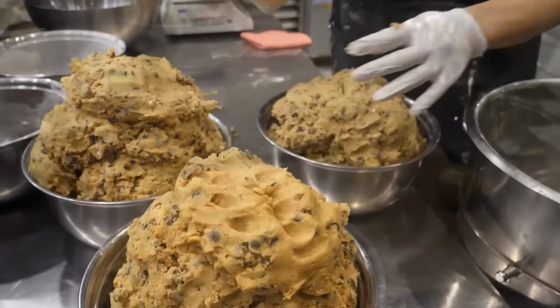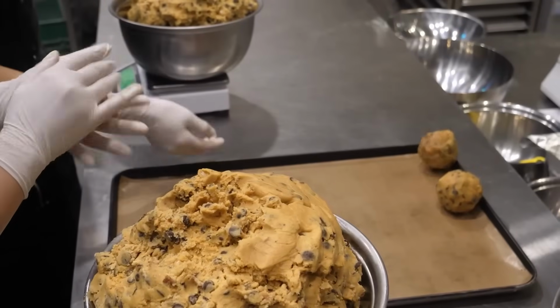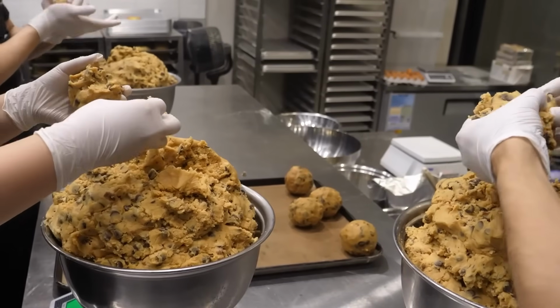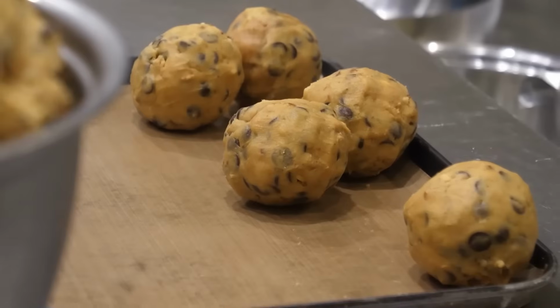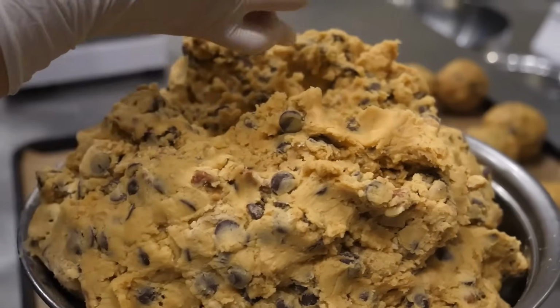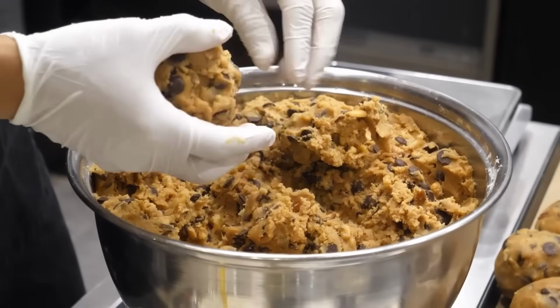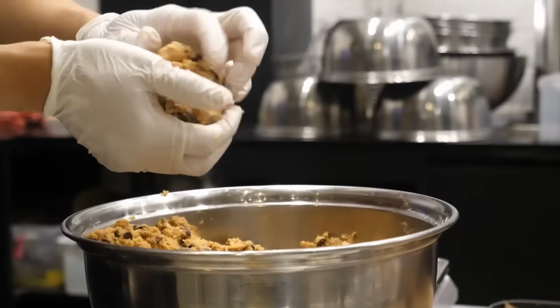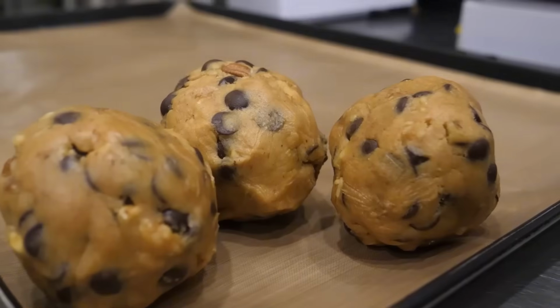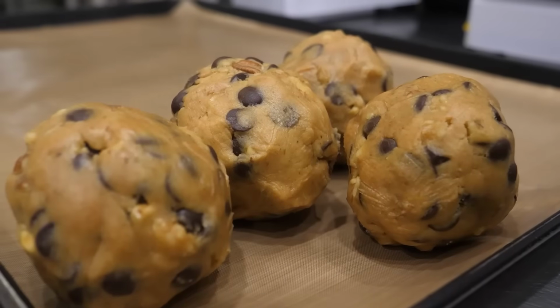Once mixed, the dough often goes through a short rest. Rest allows flour hydration to complete and lets the dough firm as fats stabilize. Rest also reduces stickiness and improves portioning accuracy. Dough can be held in a cooled hopper to maintain a consistent temperature band. Consistent temperature is critical because it affects extrusion rate and cookie spread.